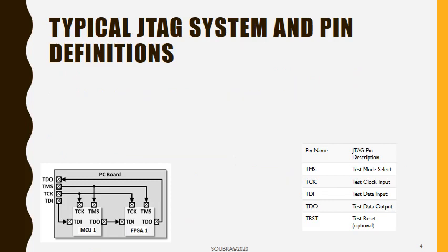Alright, so one of the questions that I asked is to describe this particular schematic. You can notice that we have an MCU and an FPGA on a board, 2 different modules, and you can notice that there's a way to talk to those different modules, and we try to understand them to guess first their functionality and what is needed in order to be able to test, debug, etc. So first thing that you can notice here, using your experience now with DSD, CA, and now this course, is that we have something called CK. Most probably this feels like a clock.